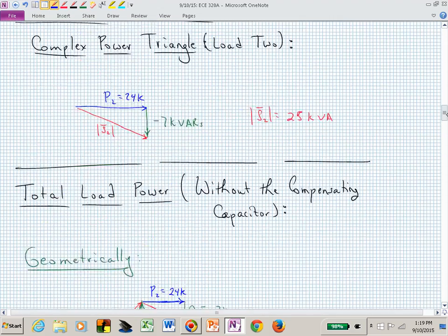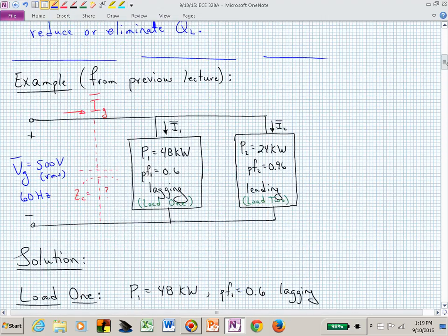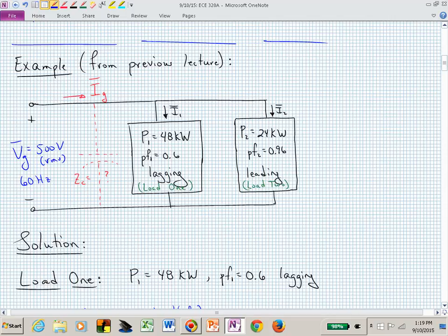So on the circuit diagram, I don't even have a circuit diagram, do I? Here's my circuit. It's not easy to do unless you start looking at the time domain characteristics of these powers at all three of those different subsystems: load 1, load 2, and the capacitor. All we can say is that the capacitor is now accommodating the magnetizing vars that load 1 and 2 are requesting.